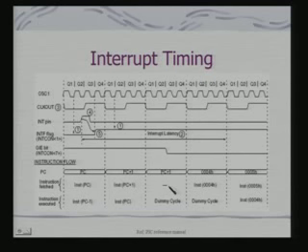in that cycle. And in this cycle, basically the instruction that you have actually fetched is not being used. So, in instruction fetch there is a blank over there, and the PC is effectively set to the vector address. Now, you fetch the instruction here, and here also, execution-wise, it is still a dummy cycle because you have not got the instruction to execute.